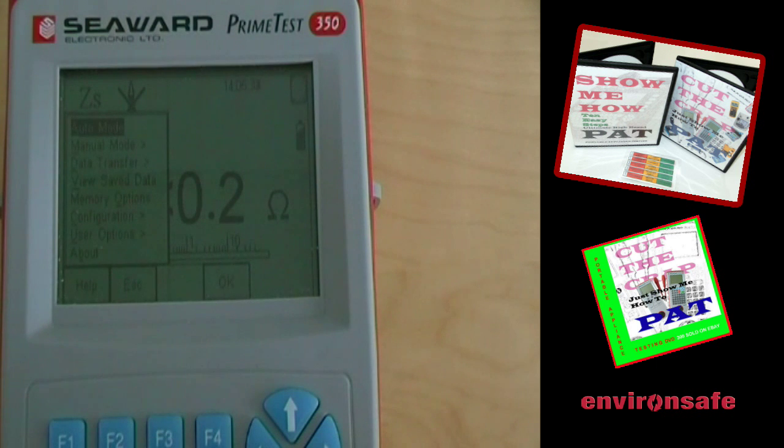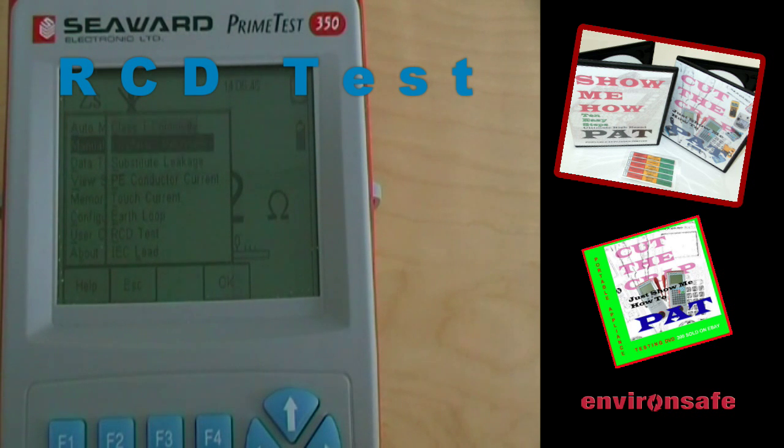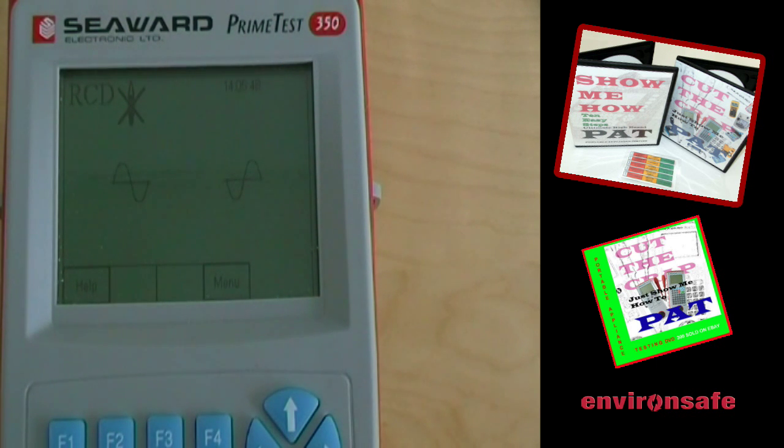F4 to go back to the main menu. Just selecting manual mode by pressing F4 again. And down to RCD test. Press OK, F4. And then there are no options on this one. The help menu, oh sorry, there's 6 pages on this one. The black probe must not be used when performing an RCD test.